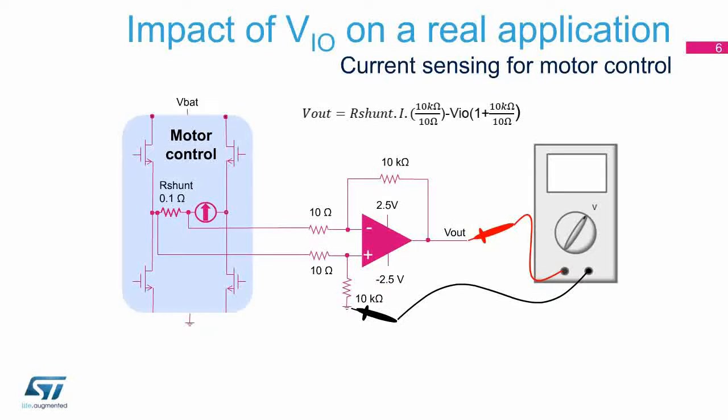When the current is only a few amps, the shunt's output signal is only a few hundred millivolts. For example, at 1 milliamp, the voltage through the shunt is 100 microvolts, to which the VIO has to be added. So the op-amp demands a very low offset voltage and drift to maintain absolute accuracy. The op-amp is used as a differential op-amp in order to amplify the voltage drop appearing through the shunt resistor. In this example, the signal is amplified by 1000.